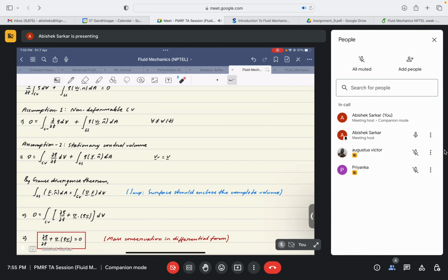Okay, here it's only mass conservation, so you are not getting any intensive property to conserve. The intensive property is one itself, but as we go to the conservation of linear momentum or other properties from now on, you will have some inherent intensive properties that you are going to conserve within these governing equations. So you need to be very sure when it is V and when it is VR. These values need to be very clear. That's why it's very important for you to know where VR is used and where V is used. Okay, just giving you an overview. Eventually you will encounter such problems.